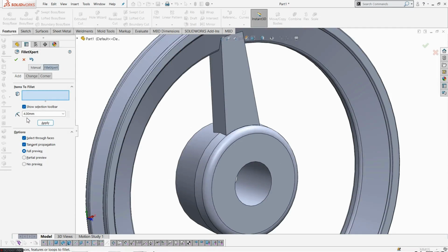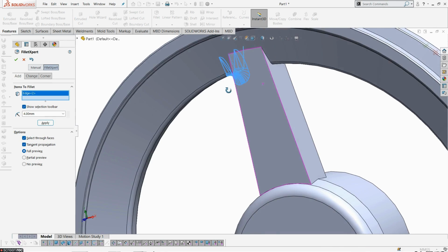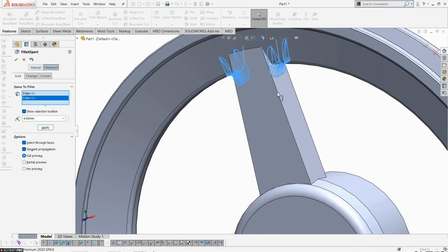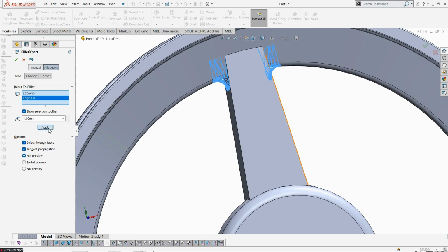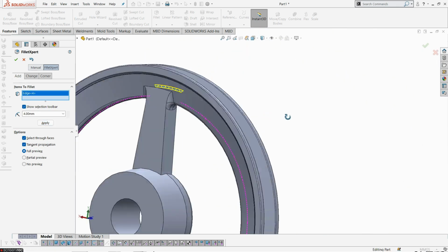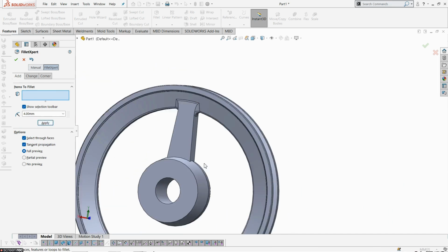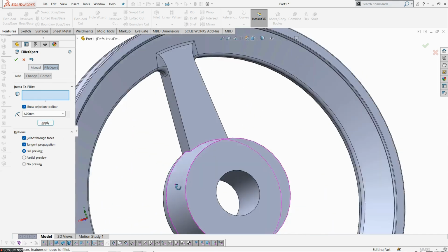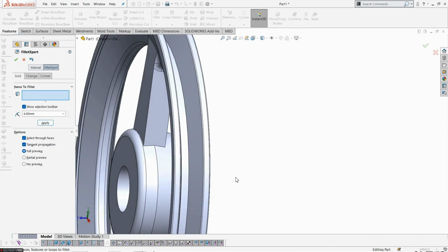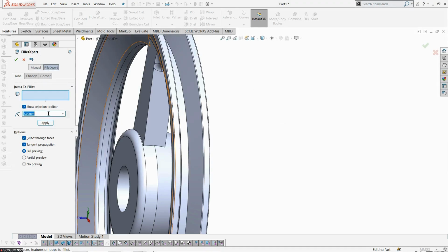Also, if you look at the top edges, in this condition also the 4 mm radius is applied. So get back into the model and select these edges. Tangentially apply the 4 mm radius. Again choose these top edges and the same radius is 4 mm. Okay. Then change the radius and select a different kind of edges. Look at it, the exact radius is 5 mm. Change the radius now and select different edges.